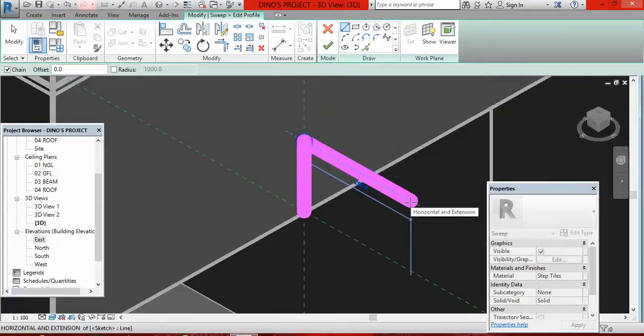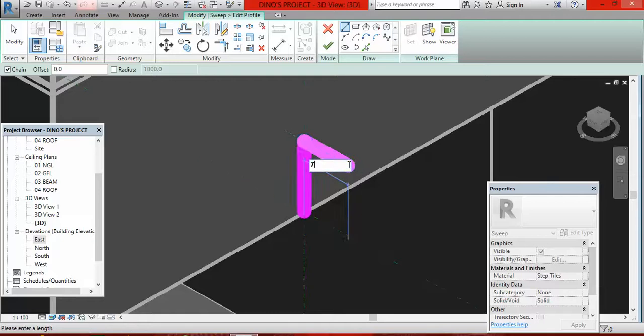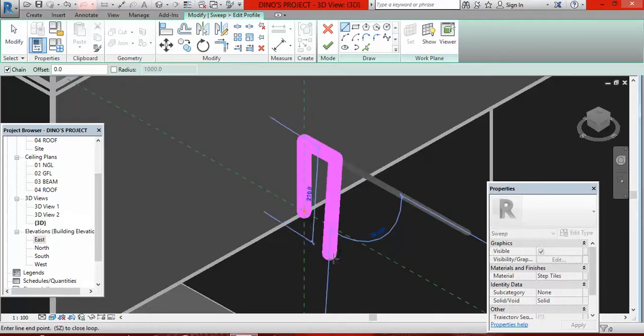If you don't see it, make sure you struggle to see it. When you see it, you can type the value, except maybe what you want to do is not supposed to be at angle 90. But if it is supposed to be at angle 90, you must make sure you see that blue dotted line. So now I type 75. I press enter. I come down again until I see that blue dotted line. The blue dotted line is appearing now. I type 35. I press enter.